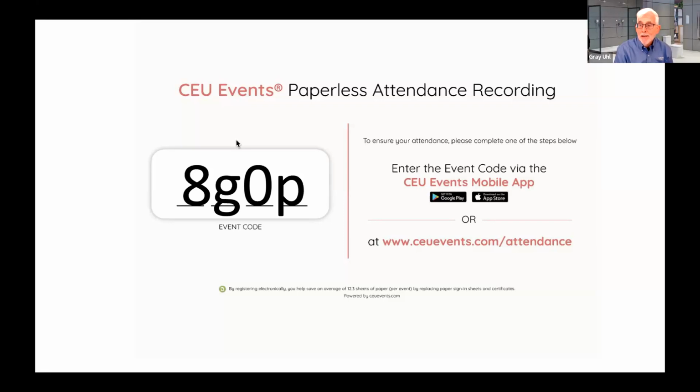Yeah, you're absolutely right. The less water flowing through that valve, the longer it takes to react to a change if a dangerous situation has occurred. That's one issue. The other one I want to share with you, I didn't talk about it, but you probably are aware we are not allowed to make a shower head or a handheld that turns off at the head or at the handheld. Not allowed to do that. It must continue to trickle water.